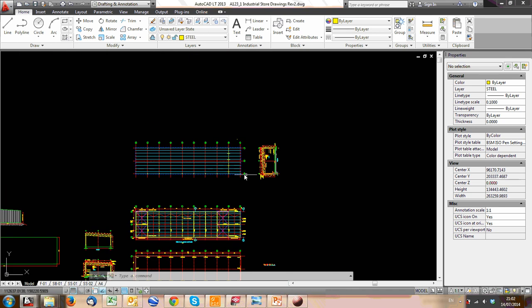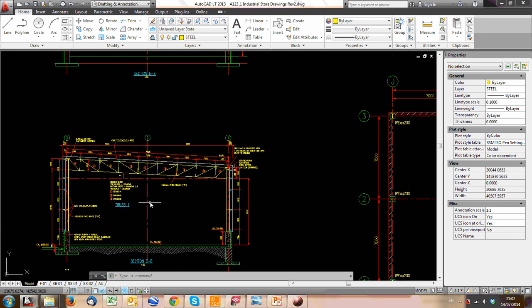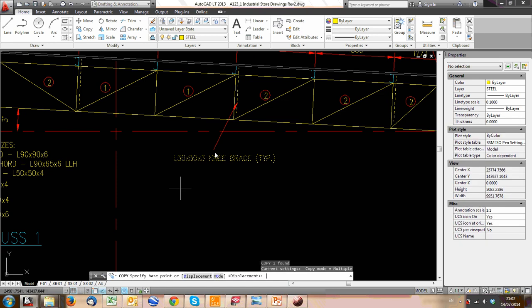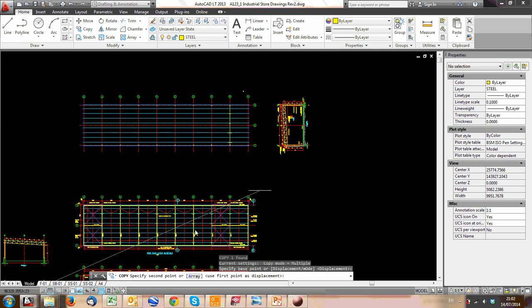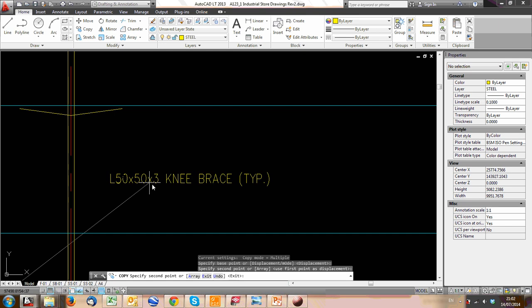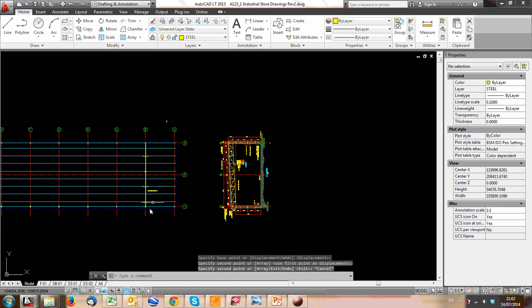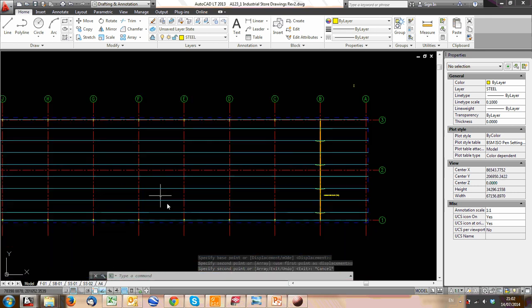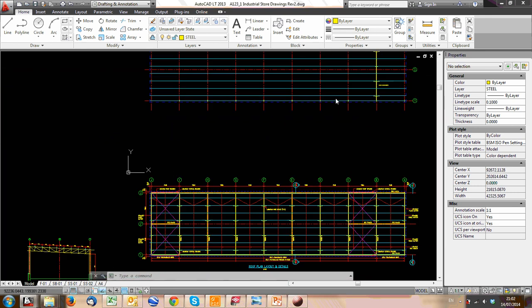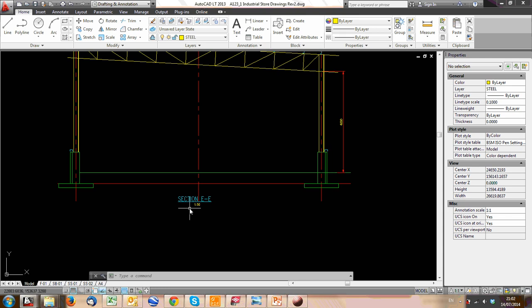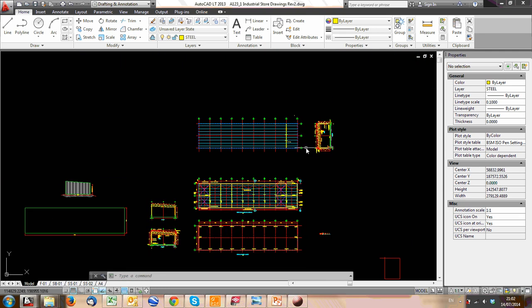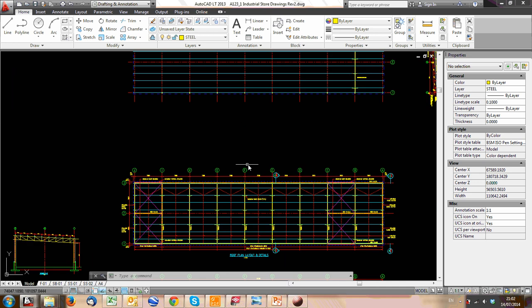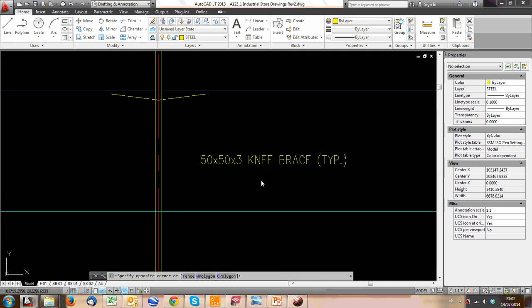First let me add in a piece of text. Now I've only done this layout, so I copy that piece of text, CO copy, or Control C, Control V, up here. This was from a 1 in 50 scale, but now I'm drawing on a 1 in 100 scale there. For a plan view, it's normally 1 in 100. For a section, you're normally 1 in 50, 1 in 100, depending on the size of the building. What I want to do now is convert a 1 in 50 scale to a 1 in 100 scale. So this is half the size it should be.